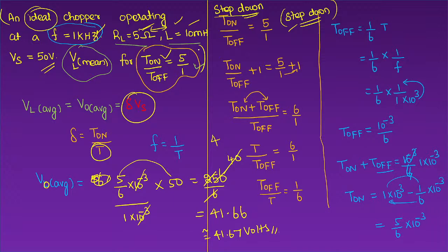If you do remember the equivalent circuit in your mind, then it is very easy to predict the nature of the circuit. Because the moment they give the data that this is connected in series with this, you can easily identify what type of circuit it is. If there is no information like that, and they have just given that there is an ideal chopper, this is the input voltage, this is the frequency, this is the resistor, this is the on time and off time, in that case, you can treat that circuit as the step down chopper generally. Okay, I hope now you might have got the conclusion about it.